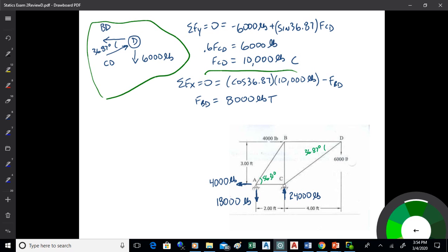Question: so when the force is traveling to the joint, it's compression, and traveling away, it's tension? Yes, right. My general rule of thumb is compression pushes on joints, tension pulls on joints. That's how I think, but your way of wording is fine too. And that's one of those things you can write on top of a test if you need to. There's no problem there. I remember learning this stuff. I repeated that to myself about 100 times just to get it, because funny things happen on a test sometimes. You start thinking too much or whatever. So get it figured out.